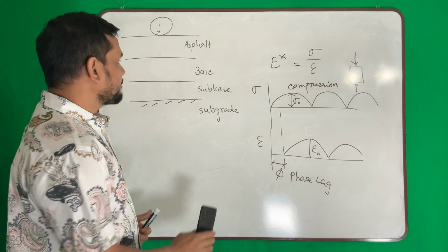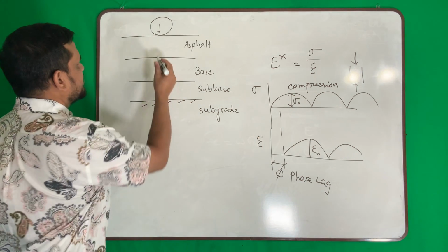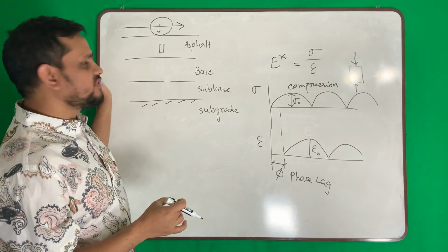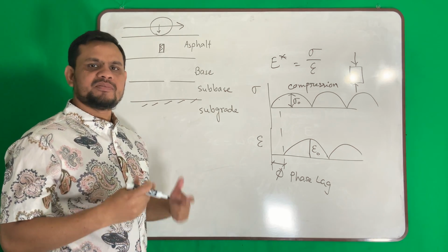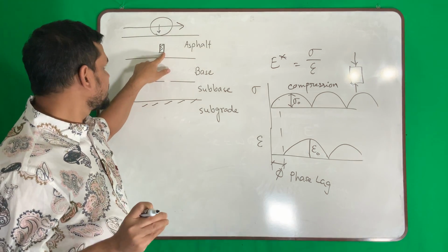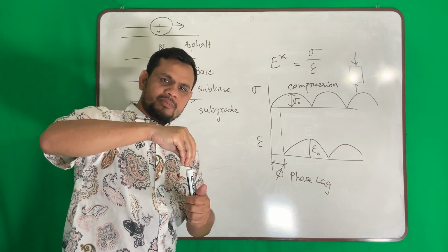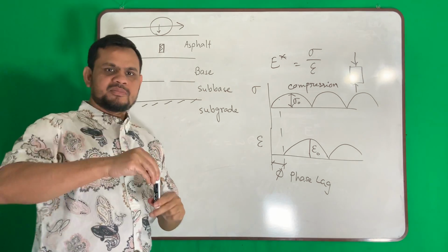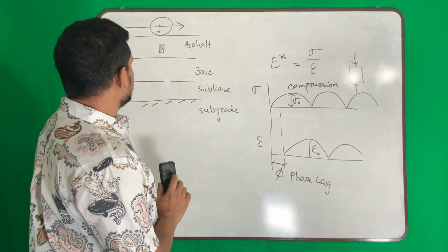Okay, then the other question is, why do we apply this kind of load? The reason is, say our material is somewhere here. When traffic comes and goes, it goes very fast. So the load applied on this material is similar to this, not exactly, but very similar. And we cannot apply any static or monotonic load, where you apply some load and keep applying. We cannot do that. Here, my load application is very fast. So it comes, goes. This is why we apply this kind of load.